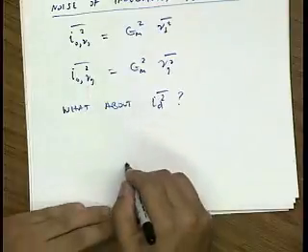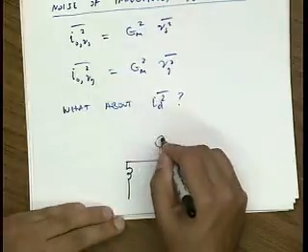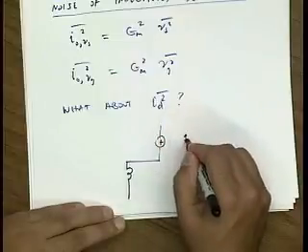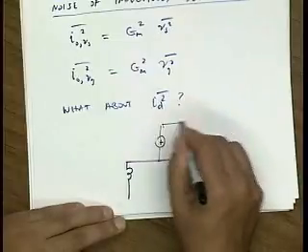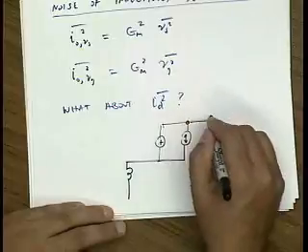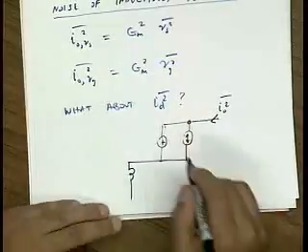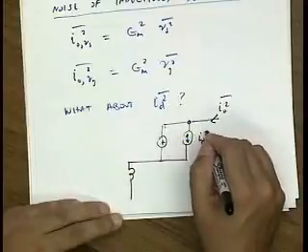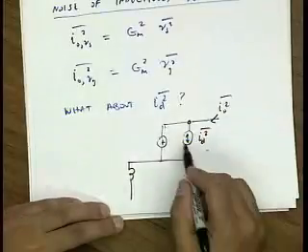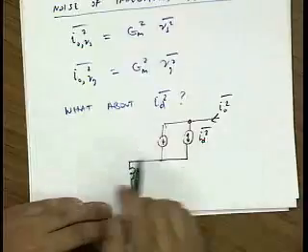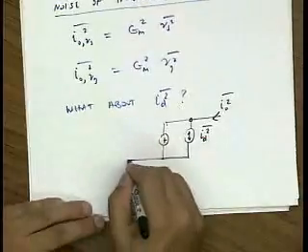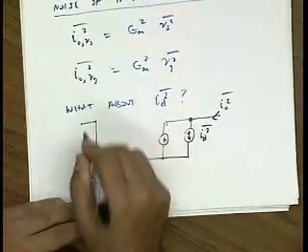So let's draw a picture here of what's happening. If I look at this current, and I'm just concerned with this current source, the drain noise, then by superposition, of course, I can set all the other noises to 0 and just focus on this noise source.